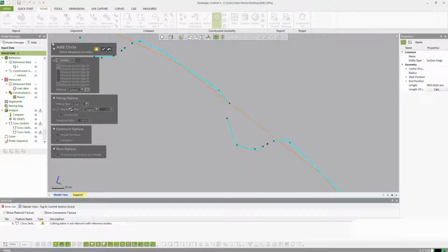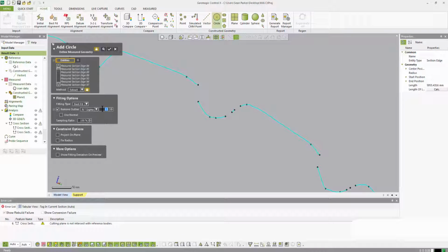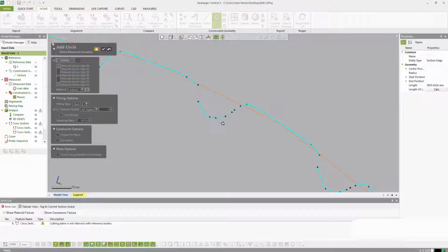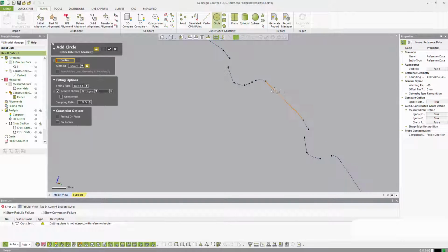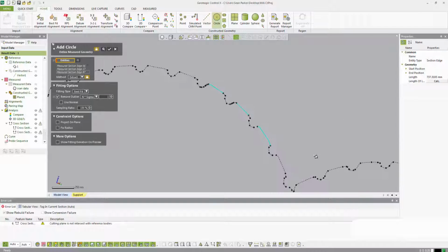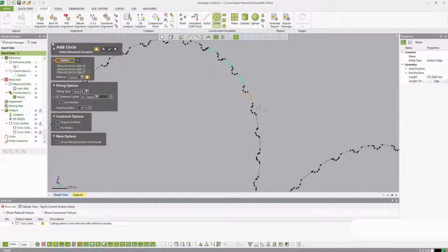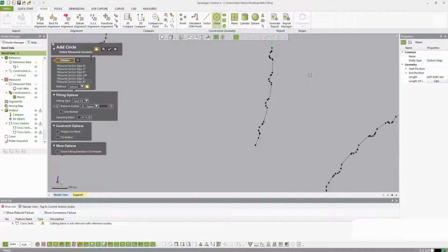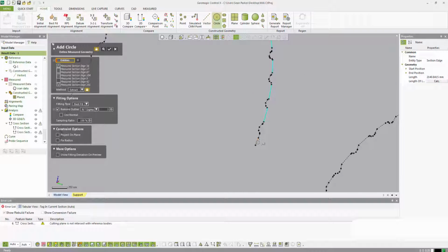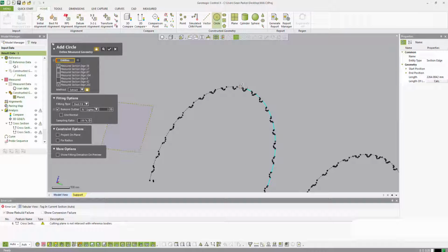And I've done a little bit of outlier removal here, and that's going to hopefully make this a little more accurate. If I do enough of it, like playing with my sigma values here, I can make it start to ignore these dips, these grooves between these risers, whatever you want to call them, and just extract from these top surfaces. Now I could also just manually go around and click, boom, boom, boom, and this is obviously time consuming, but I can ignore some of the other pieces of data as well. So however you really want to do this, it's up to you. Don't really care. This seems to not be taking that much time.